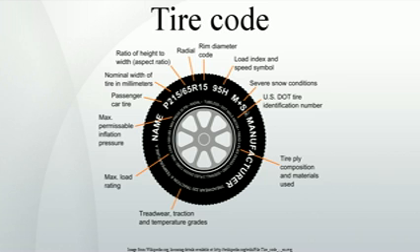Suggest not using a new tire that has been sitting on the shelf for more than 6 years, Ford Motor Company, or 10 years, Cooper Tire, citing a Tire Association recommendation. JATMA, the Japanese Automotive Tire Manufacturers Association, recommends that all tires be inspected at 5 years, and all tires that were manufactured more than 10 years previous be replaced.